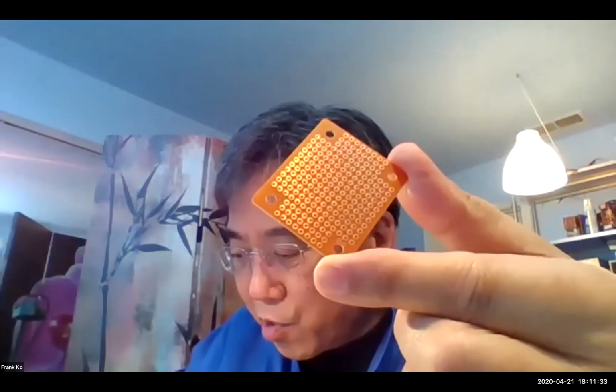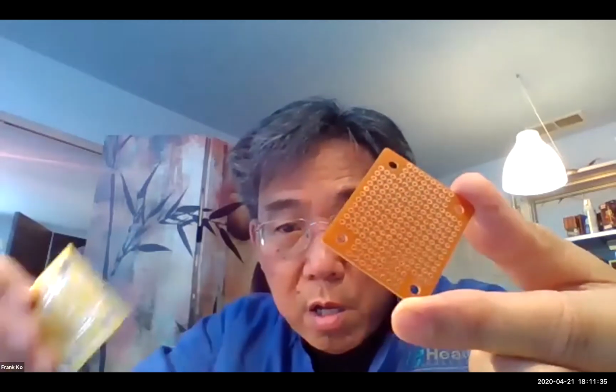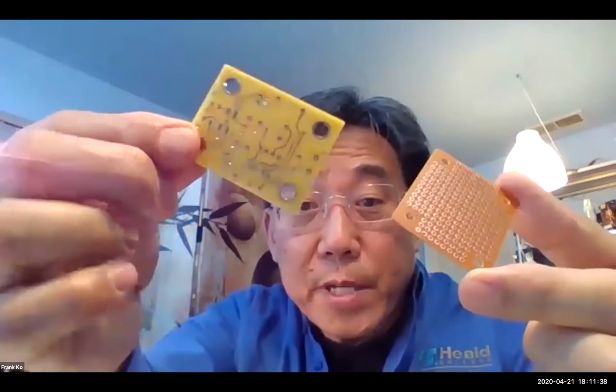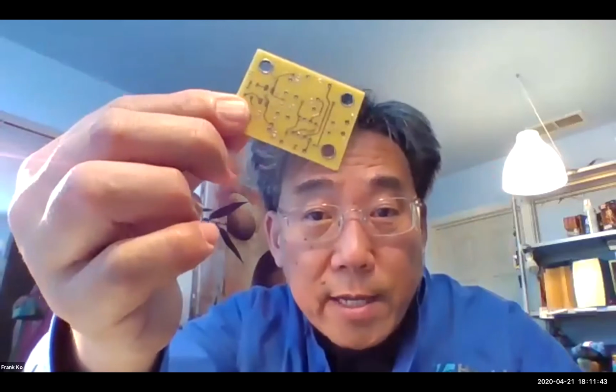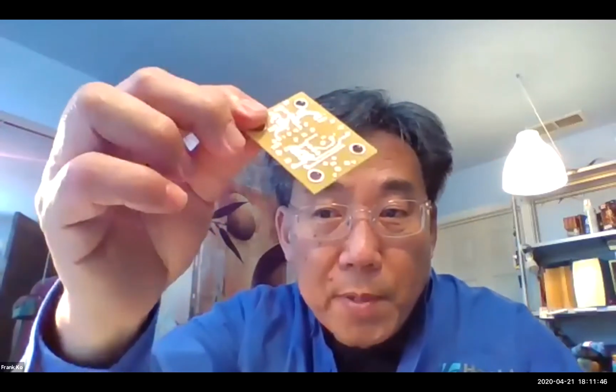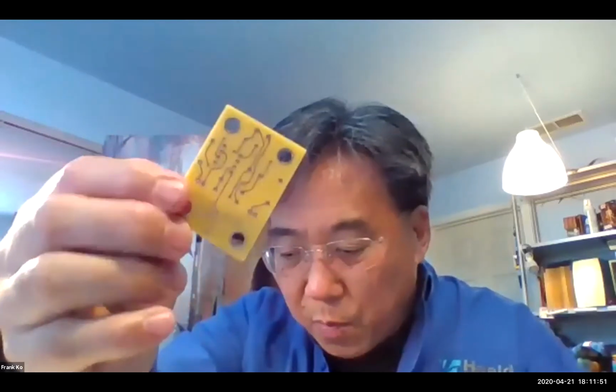Well, if you compare these two boards, you might say, wait a minute. On this board that we have this week, there happens to be a trace pattern, which is nice. That means all of the wires for the components are interconnected with each other, and all we have to do is pop in the component, solder the ends like we have been, and everything is hunky-dory. The thing we do have to remember, since we are soldering this chip directly onto the board, is to be sure not to heat the pins too much such that they burn out the chip.